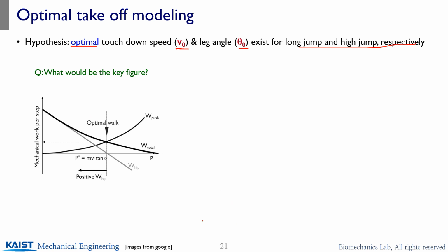point of view. So for example, in the previous chapter, chapter 2 on locomotion, we examined what is going to be the best, least costly push-off magnitude for bipedal walking, right? As you keep increasing the P, your total mechanical energy decreases, but within some constraints, having positive hip joint work, we found some energy efficient walking conditions for the push-offs. So even though I say it's an optimal walking, it's more like least costly walking from the mechanical energy perspective.